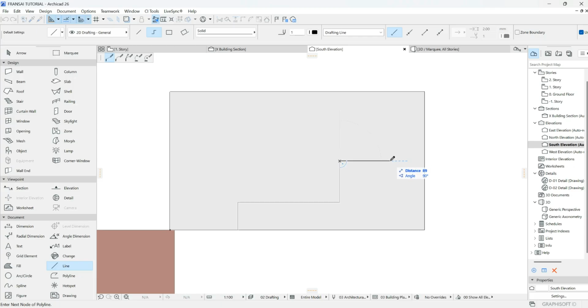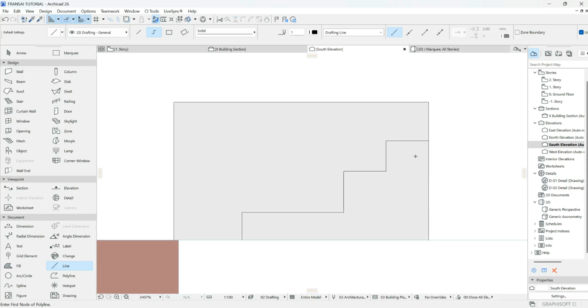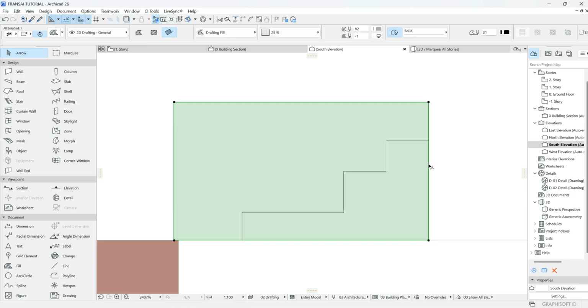parapet. Let me say 75, enter. Okay, let me say 55, enter, and that's all. So this is how we can create the step parapet. Can equally do just maybe 2 step or 3 step, depending on how you want the design to be. So let me just edit this field now to enter these particular steps.